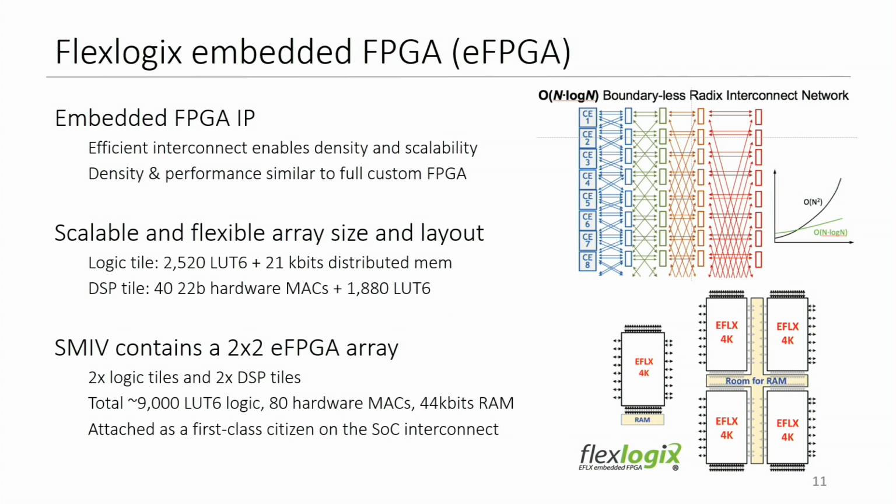And there are various use cases for embedded FPGA in SoC products because quite often we'd like to be able to reconfigure things post-silicon. But the approach we took, and we're particularly interested in with this, was to use the embedded FPGA as a standalone accelerator, which can be reconfigured. So it's a really interesting point for us on the efficiency versus flexibility scale.